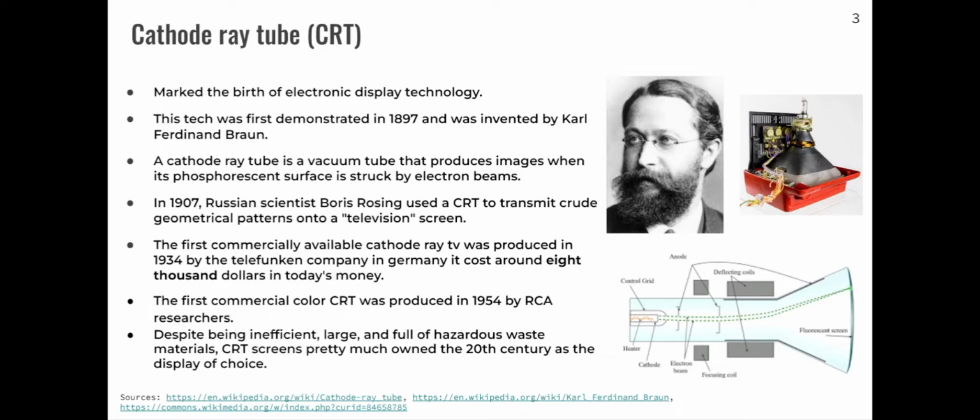The reason CRT TVs were so heavy and bulky was that they consisted of an electron gun. The way the CRT works is that this electron gun would fire electrons into an array of millions of tiny blue and green and red phosphor coated dots. The beam would fire horizontally row by row, and when the tiny phosphor dots were hit by the beam, they would glow. So when you do this rapidly enough, you can form the illusion of a moving image.